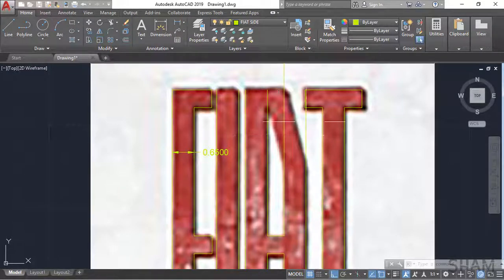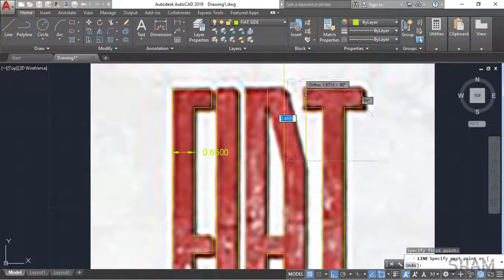To create that part, first you need to remove the constraint. Click on Ortho. This will remove the cursor from only moving orthogonally. Adjust as you see fit in this case.